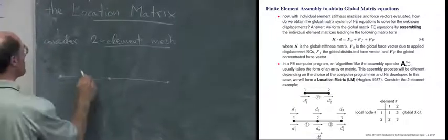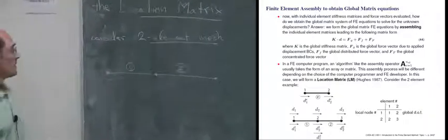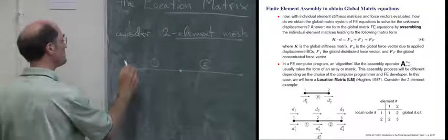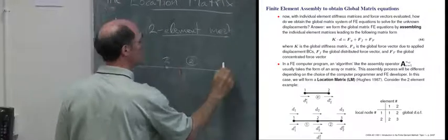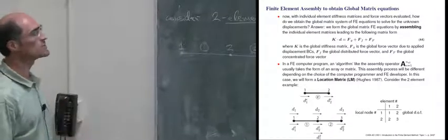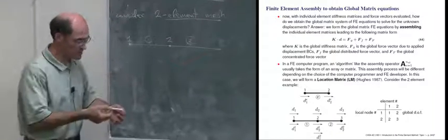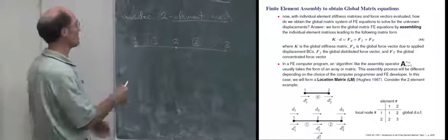So we're going to label this element 1 with a circle and this element 2 with a circle. And you can see there are 3 nodes, 1, 2, and 3. So without considering boundary conditions at the moment, we may have 3 global degrees of freedom for axial stretching of our bar, so stretching of the chalk.